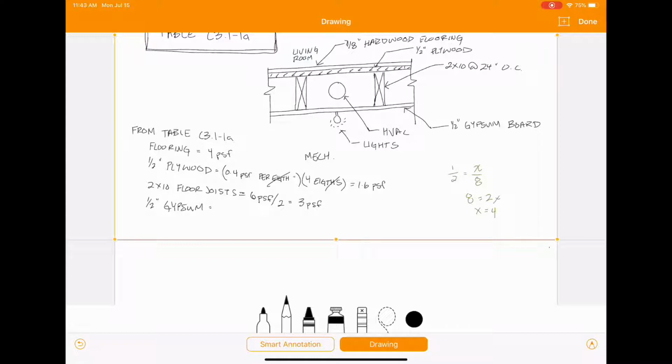Make sure you don't pull it from your wall covering section because the values are going to be different, because a different amount of plaster is used on the ceiling versus the walls. So go to your ceiling section. It's the second one from the top, and we can see that it's per 1/8 inch thickness again.